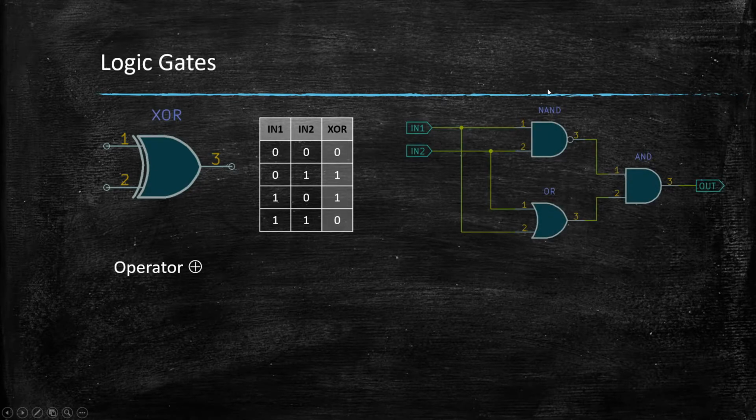So the easiest implementation is you have a NAND, an OR, and an AND gate here, which will basically replicate that functionality: A and not B, or not A and B. And you might see that we don't really replicate that function down here. That is simply because you can simplify that into what you see up here with the NAND, the OR, and the AND. You can basically factor out stuff and put it together so that it represents this formula that is displayed up here.